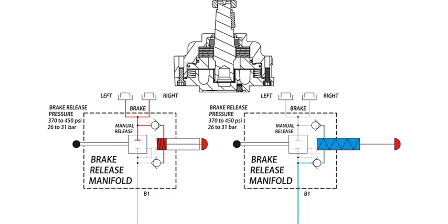Repeatedly pressing and releasing the hand pump forces more oil into the brake, acting against the brake piston. When approximately 400 pounds per inch squared is applied, the brake piston overcomes the spring tension, freeing the friction discs, allowing the shaft to spin freely.